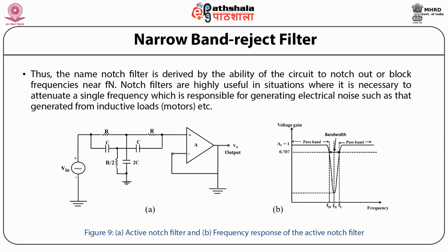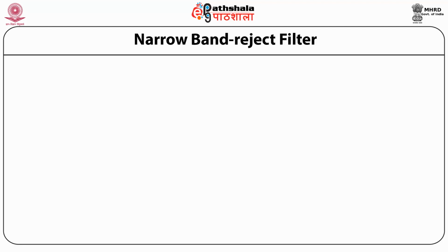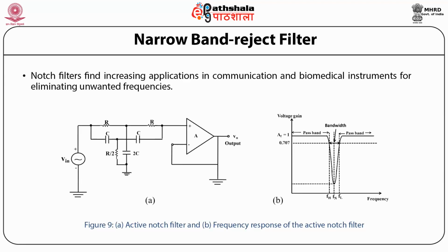Notch filters are highly useful in situations where it is necessary to attenuate a single frequency, which is responsible for generating electrical noise such as that generated from inductive loads, motors, etc. Notch filters find increasing applications in communication and biomedical instrumentation for eliminating unwanted frequencies.